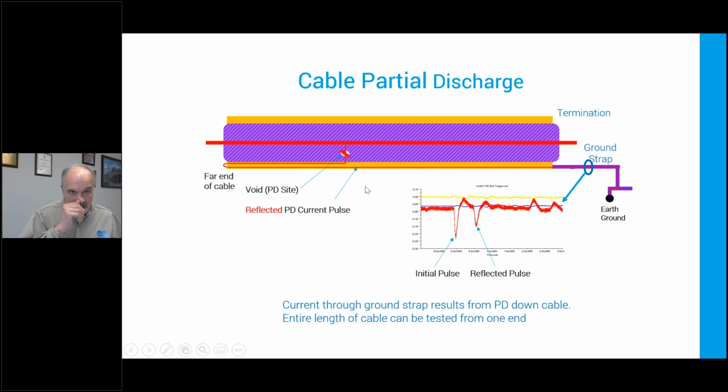So what we can do is, if I'm looking at the cable and I'm looking at the shield, all right, so I've got discharge to the shield, or I have discharge outside the shielded area, but the pulse is coming from the conductor, and it radiates into the shield. One of those two is going to cause a signal on the shield that wants to go to ground.